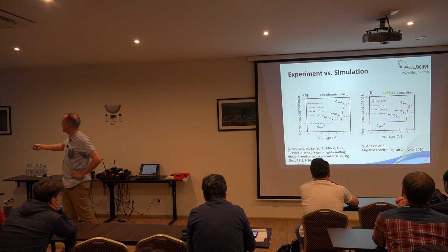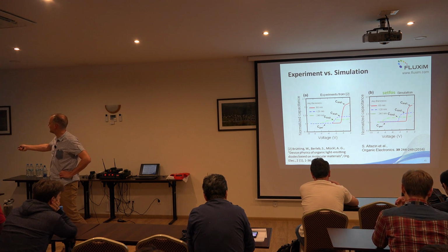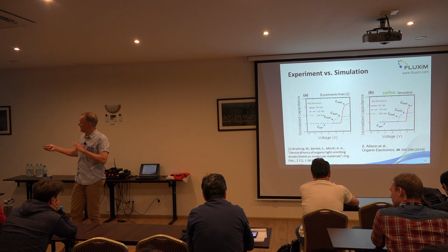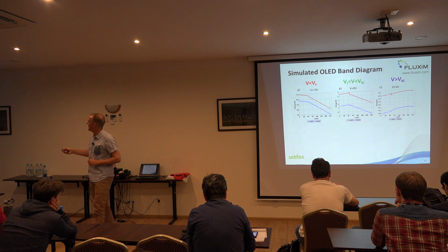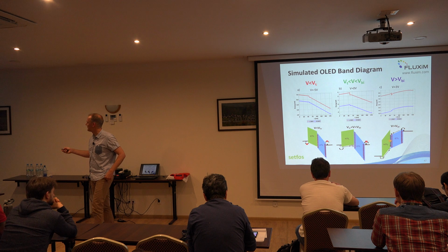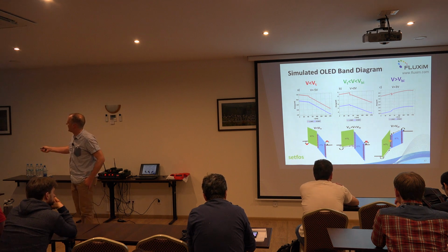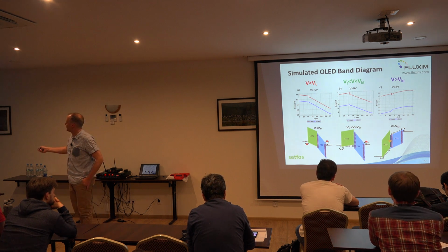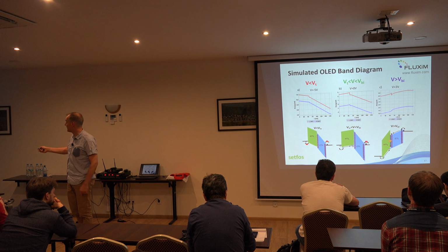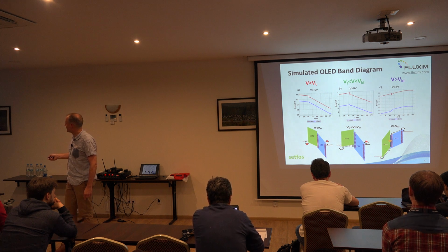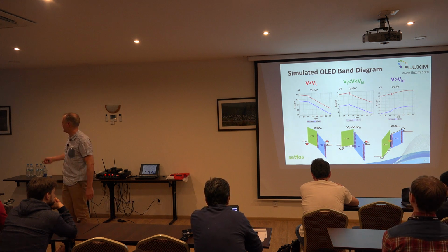If you are in this regime of elevated capacitance value, at that specific voltage range, then the band diagram looks such that the electrons would have to go uphill, so they will not be injected. But the holes want to go uphill in the band diagram, so they are injected, and they pile up at this interface, and this defines the higher capacitance value.